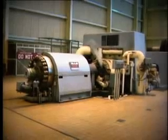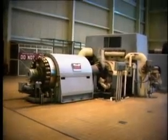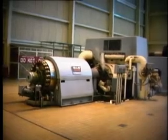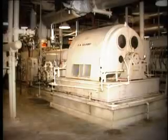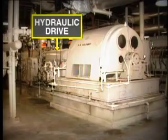The steam turbine has the obvious advantage of variable speed control, which can be used to adjust the quantity of water being supplied to the boiler. Of course, the same result can be achieved by applying a variable speed hydraulic drive between an electric motor and the pump. The ability to control the quantity of water being pumped into the boiler is vital for safe boiler operation, and the control system must be able to respond rapidly to changes in water level in the boiler caused by variation in turbine load.